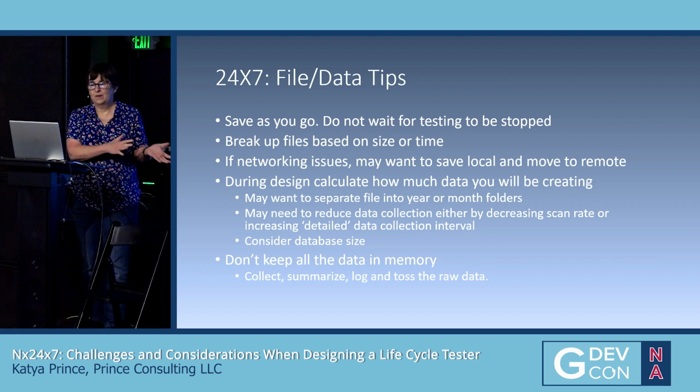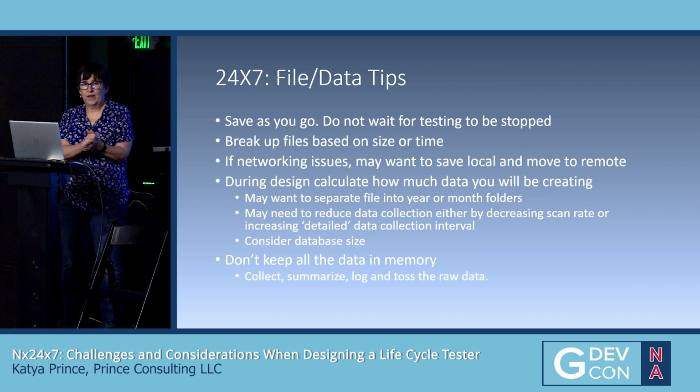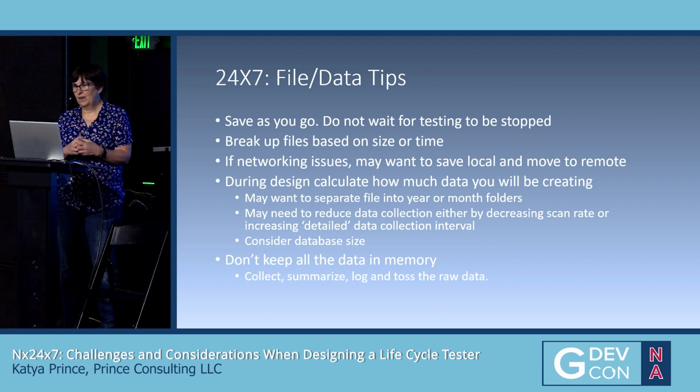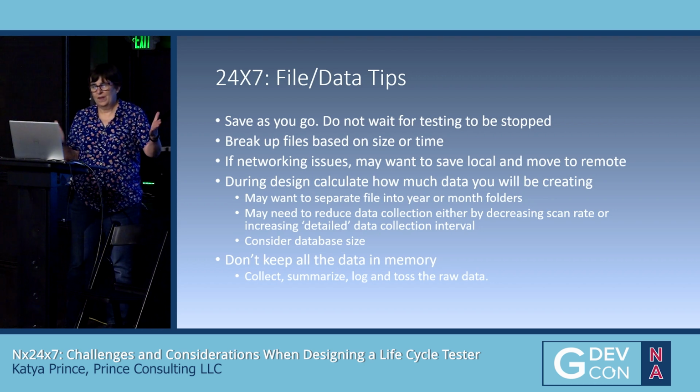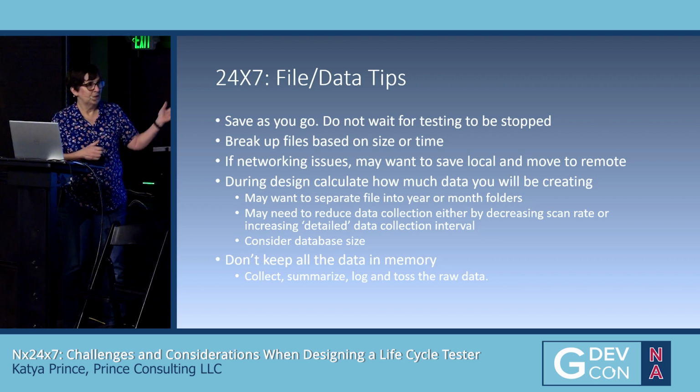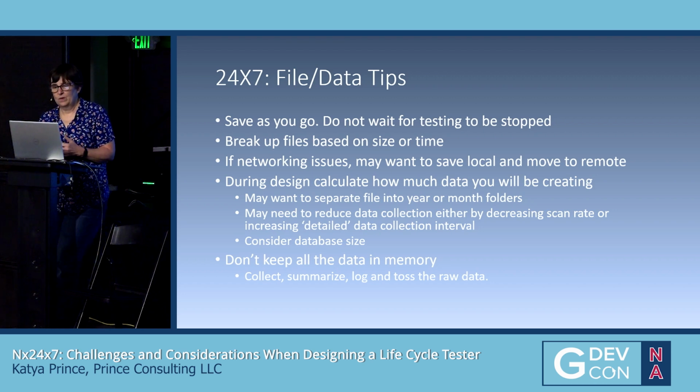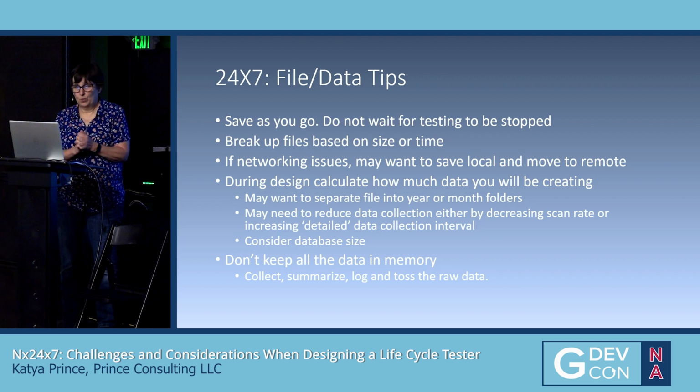And when you're designing it, you want to sit down and actually calculate how much data you will be creating and wanting to save. It's one thing to say, well, I have this one test, I'm going to collect it at 100 kilohertz. Well, 100 kilohertz times 10 seconds times 5 times a day times, you have to start calculating that to make sure that you're not going to run out of space. Hard drive's not as big a deal, but for the database, you need to consider that you're going to have enough room in your database for that kind of stuff, if you're doing that.